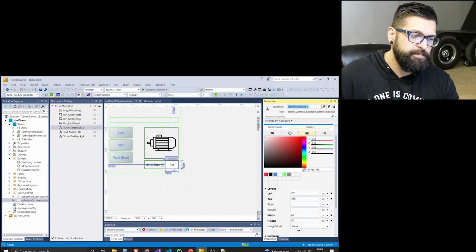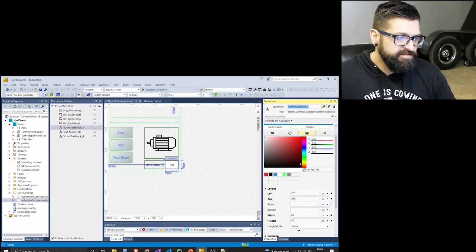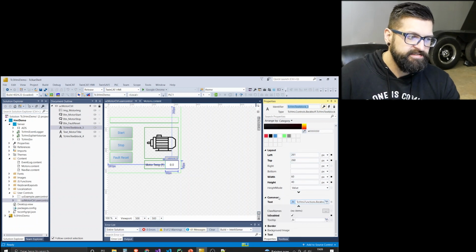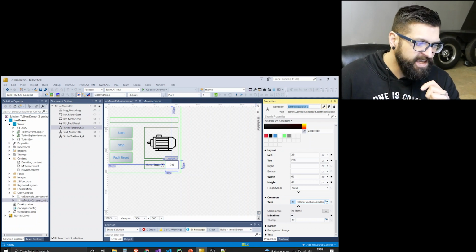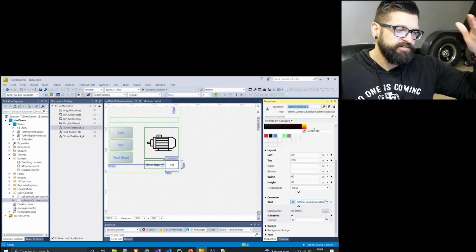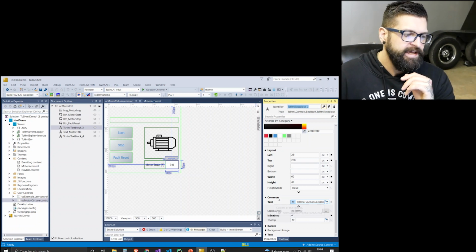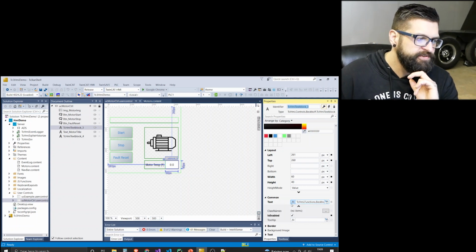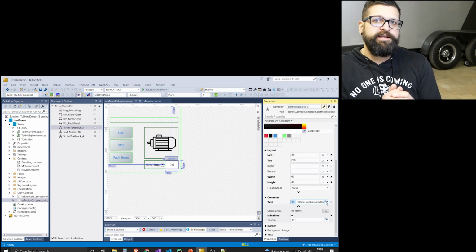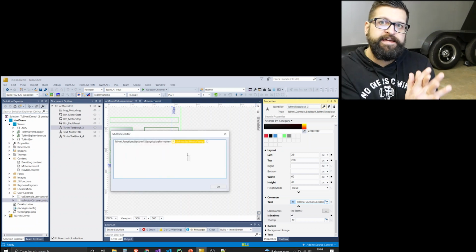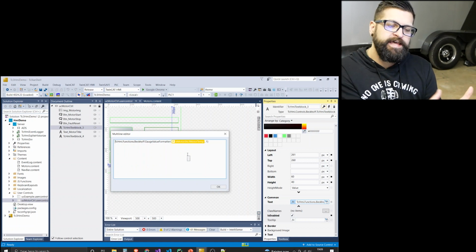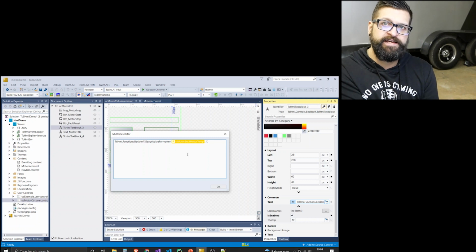I must be acting on a property. And if I scroll down, I can see in this text block, if we look over here, it's a type TcHmi controlled text block, meaning it displays text. And over here, it says common text. Okay, so under the common class, we have a text property. And if we click on this, what I'm doing is, because I'm not displaying necessarily native text from the PLC, I have a real value. And as we know, not every floating point real value has a nice terminating decimal representation or binary representation.